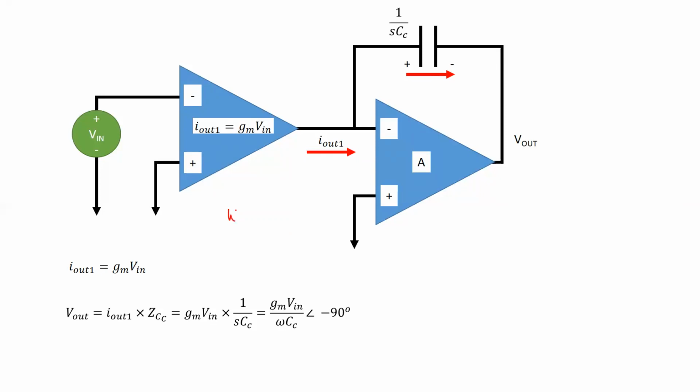Low pass filter, right? Omega naught over S plus omega naught. If I don't have this feedback capacitor there, what does this lead to? E to the minus t, right? Decaying exponential, because the root, where does this equal 0? Minus omega naught.